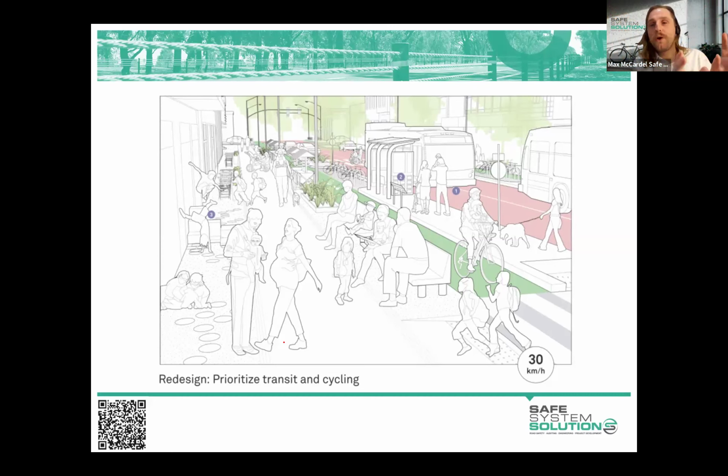So it still requires the project team to review that, to either accept that, say, yep, we can do that, or no, that's not feasible, and then to deliver on that outcome if they decide to. So let's say they decide to go with the one-way treatment. They would then create another design drawing where generally within industry, a separate road safety audit would be completed for that product. I would say that's fairly well embedded within industry to have that conducted.